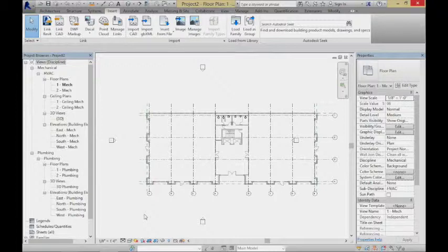And we can do that by using something called copy monitoring, where I'd really like to copy something out of the architectural model and have a copy over in my model and have it monitored. So if anything changes, those two things are always going to stay in sync. What I'm trying to do is make a copy, just give me a little bit of independence, but also have a link back so that I always have notification in case anything changes. So as a principle, how does that sound? That kind of makes sense? I'd like to make a copy of your thing, but you can still change it. I'm just going to get notified if you change it.